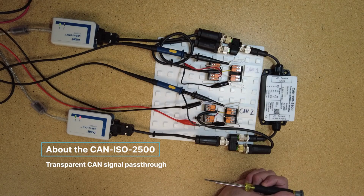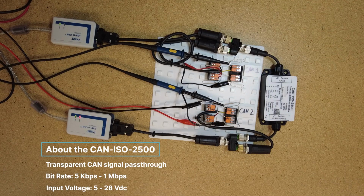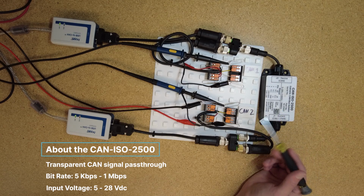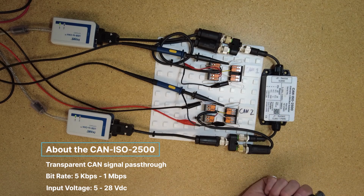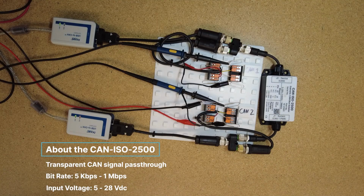We test this device at anywhere between 5 kilobits per second to 1 megabit per second. One of the advantages of our product is that you don't need to set that. Because it's a more passive CAN device, it just passes the data through. The device will work at any of those data rates without needing to configure it.